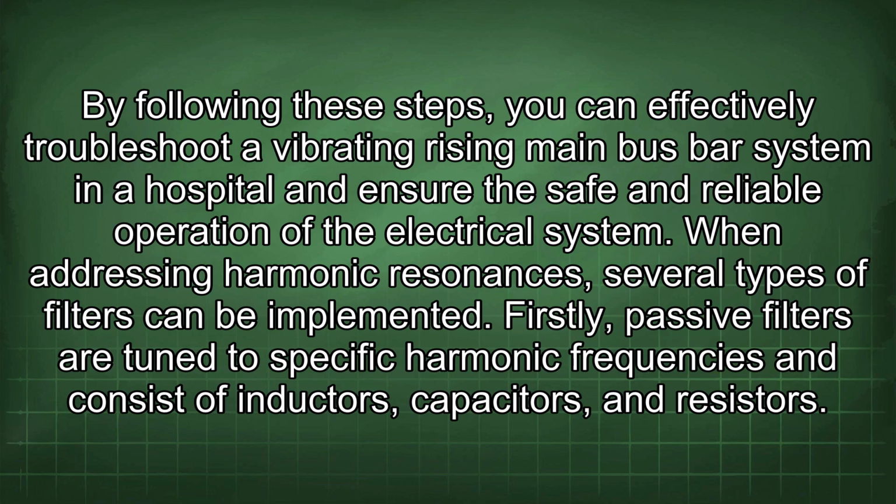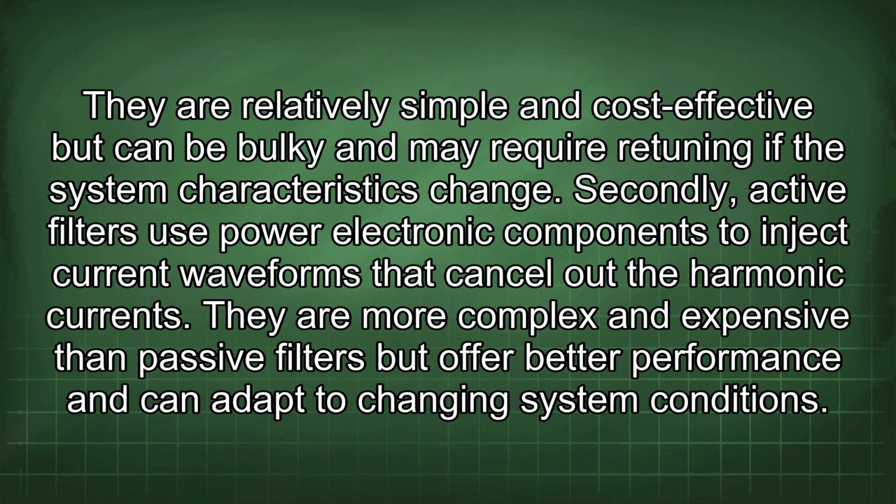When addressing harmonic resonances, several types of filters can be implemented. Firstly, passive filters are tuned to specific harmonic frequencies and consist of inductors, capacitors, and resistors. They are relatively simple and cost-effective, but can be bulky and may require retuning if the system characteristics change.